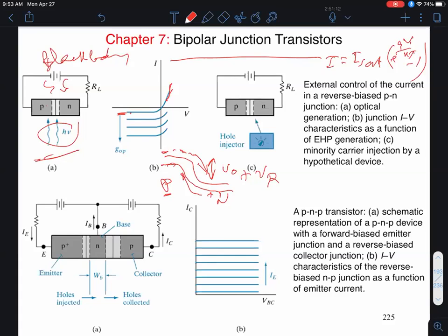And what ends up happening is, as I increase the reverse bias and the electric fields go up, normally you would think that these reverse currents would increase with electric field, but in this particular special case, it doesn't, because it is supply limited. Do you remember the term? So this reverse current doesn't depend on how fast they flow across, but how often they're supplied to the edges of the depletion region, okay? And that supply is limited by this black body radiation. That's what generates your intrinsic carrier concentration, Ni. Hopefully that jogs your memory, right?